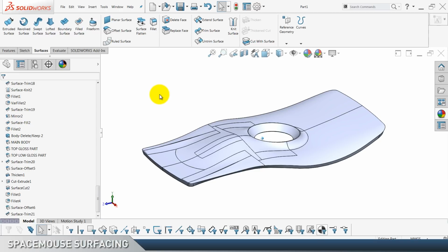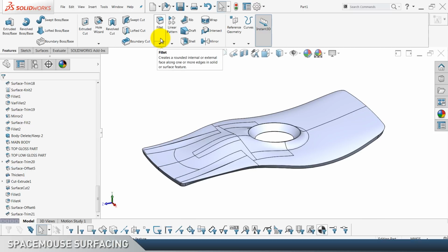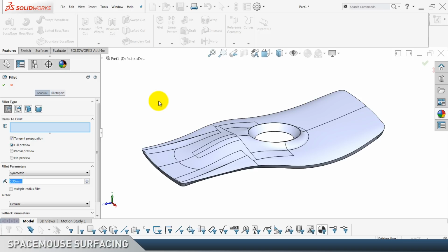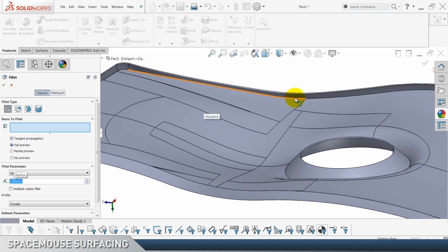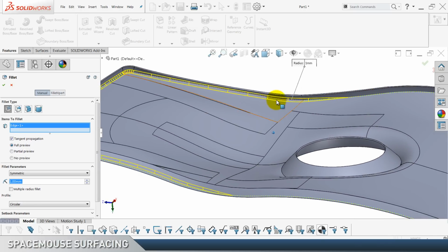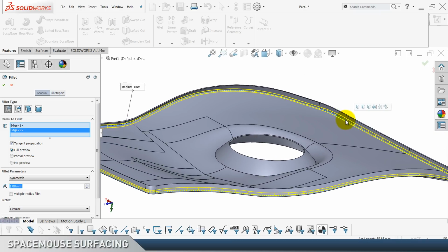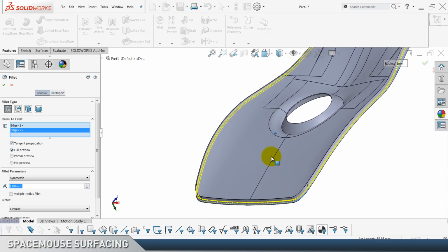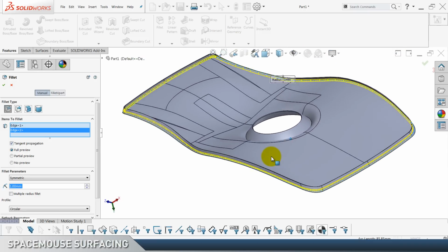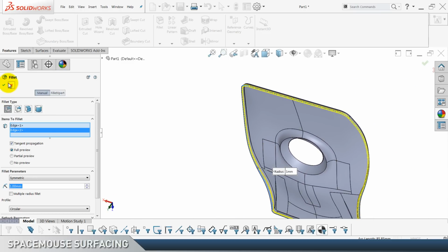and we can now make fillets. So actually let's do first this one, R1 for this inside edge. As you can see, we're gonna have to select multiple edges just to make sure that this fillet is going all around this inside looking surfaces or faces, and it's gonna work.